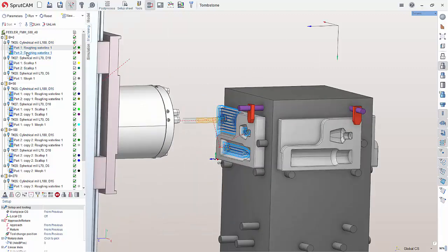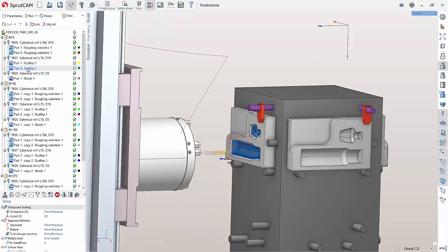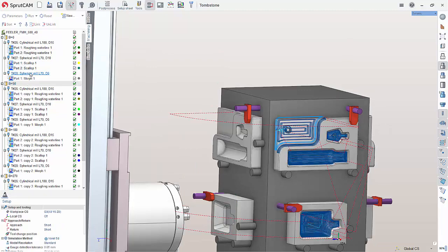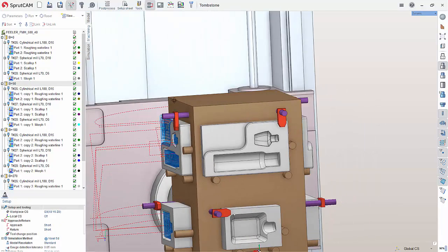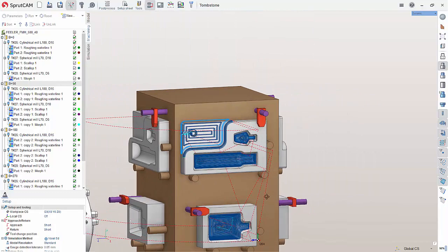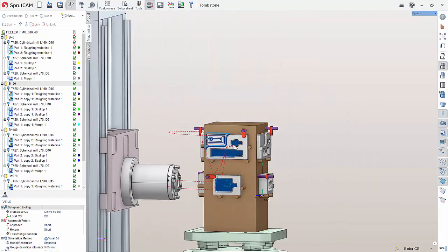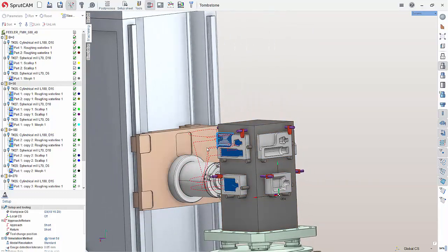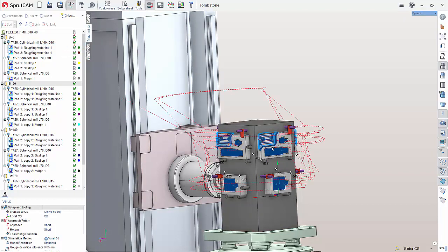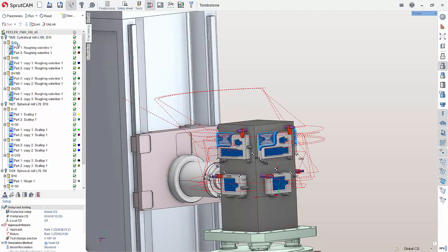All right, doing that, and then it does the other one. Okay. And then it moves to the next side and does this side in completion. Now, again, you may choose that side is top priority. You want to machine all on one side and then move to the next. Or because it's a rotary, you may decide that tool is the ultimate priority. So you want to do all 4 sides with one tool first.